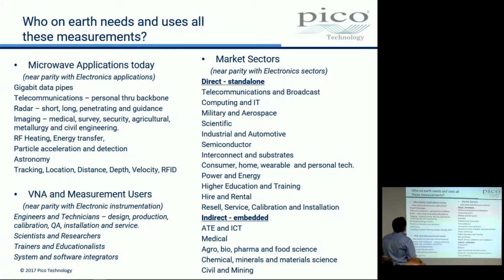Well, no, you're not. These are the applications, and of course antennas are part of that. An antenna is just a DUT. But you're quite right, that's a very, very important DUT. What does it do? It takes an electromagnetic wave from a piece of cable, and if you make your antenna correctly, you're going to inject that into the ether. You're going to match it to the ether. If the antenna were not correctly matched, you get the signal back instead of it going to the ether. So it's another DUT for a VNA. You're quite right.